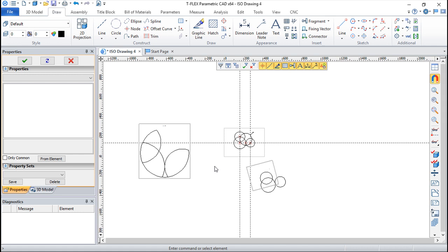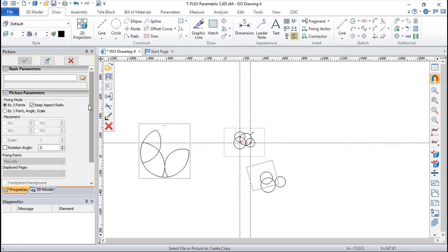In these supplementary elements, we have also the possibility to make the insertion of pictures. So if I go in this group appearance, I can say picture, and the picture, it's a basic command. So I will choose only where is my picture, and I can select it and just insert it, or select it and make it embedded. Embedded, it will take part of the drawing, so it will not have a link to any place.